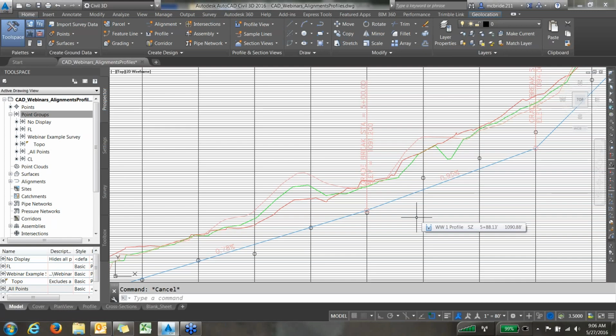You're going to have to next use these grades that are on this line and plug them into the Engineering Field Tools program, which we should all be using to design grass waterways now. If you're not, you're going to get written up in your QAR, just telling you. Plug these grades in, along with your watershed area, or the total flow coming through here, and do a pre-design on your grass waterway. So set your width to, say, 40 foot and figure out what the depth is.